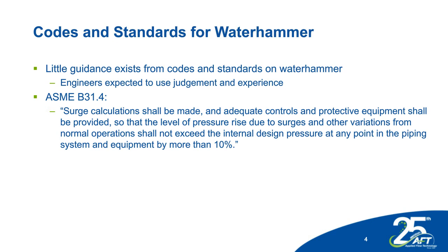We'll talk about that in a moment. In the English language, that says "shall be made," which, if you're endeavoring to comply with B31.4, means you're obligated to do some sort of calculations for Waterhammer. And there's some guidance in here on what levels of Waterhammer are allowable.